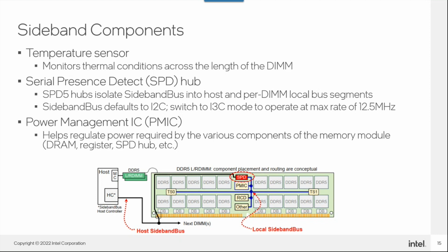Great. And one more prior question, the maximum density support for DDR5. So as per information available from Samsung, their maximum capacity is 512 GB. So they are able to compact 512 GB worth of capacity into one DIMM. So that would be the maximum. And depending on what memory format you are going for, what your base device capacity is, as well as how many ranks you have on the DIMM, whether you have 3DS versus non-3DS, that will also impact the maximum size of your DIMM capacity or interface capacity.